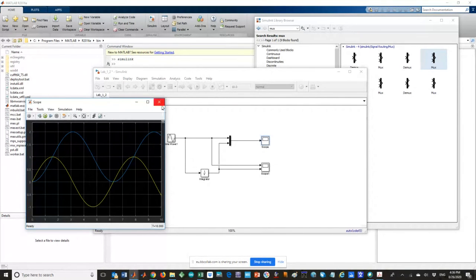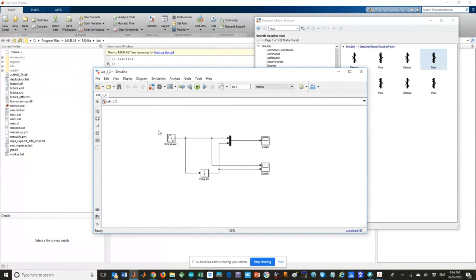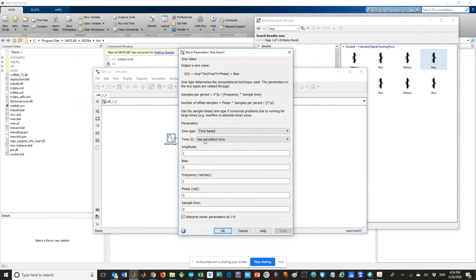yeah, there is one thing I didn't change. I'll close this. Those are the parameters for each block, but especially we have right now this block here to be adjusted. Double click on sine wave. It comes as 1 volt, 1 hertz. That's why it takes a long time to appear. 10 seconds for 50 hertz will show hundreds, maybe thousands of cycles, not one cycle or half of a cycle as it was with this one reading per second.